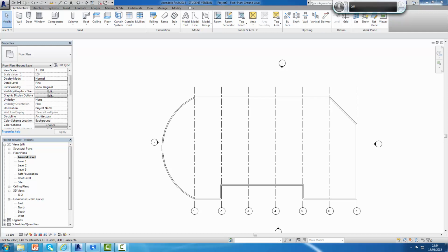I used this tool here, and then the wall type I'm going to change to the cavity wall. So that's the cavity wall we started off with, this one here, cavity 102. Okay. I'm going to select this one now, and I'm going to copy that up, paste it aligned. I'll put that on both levels 2 and 3. So we're already getting some impression of the height of this building. I'll now put walls on the ground and take them up.